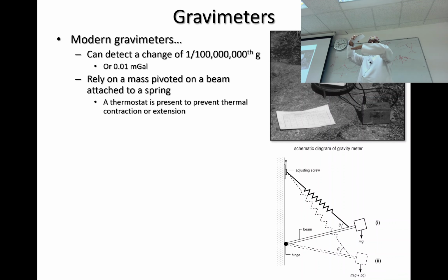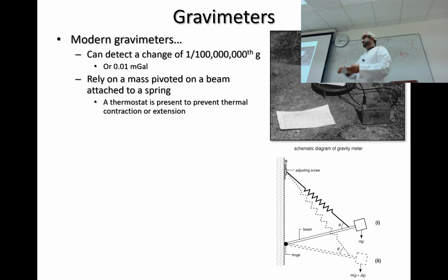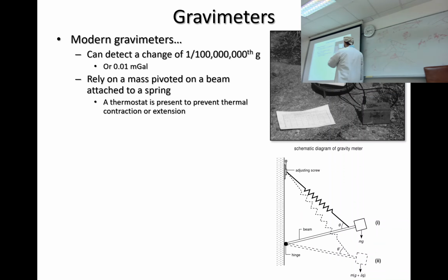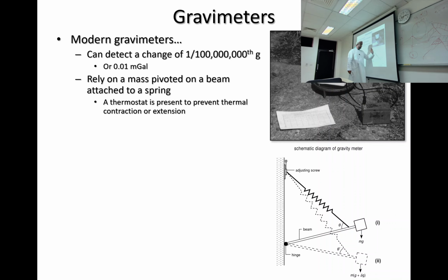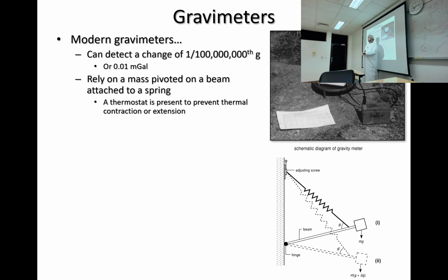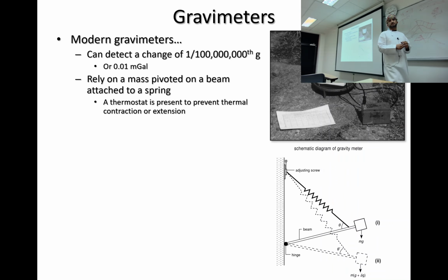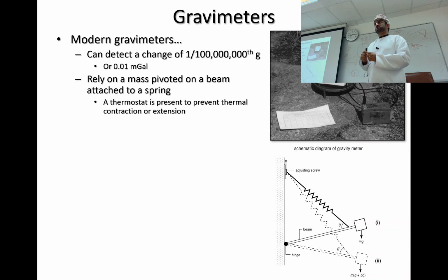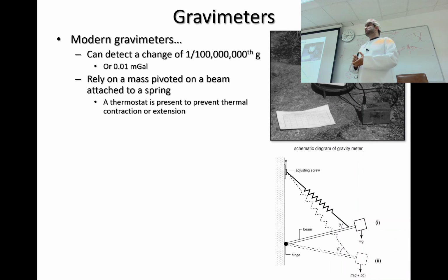This is the apparatus, and this line is where I take the measurement. If it is tilted a little, then it is no good. So you need to level your apparatus properly, with very high precision. In this one, which was manual leveling, it sometimes took us even half an hour.